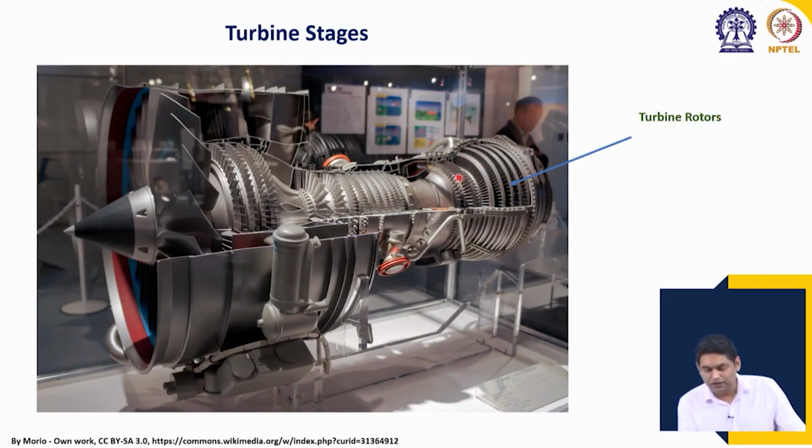Okay. And they also have similar blades, but the blades are more curved for turbine stages, and each turbine stage can undergo more pressure ratio, it generates more work as compared to the work input to a single compressor stage. So, fewer turbine stages are required even for industrial gas turbines, and for jet engines even fewer turbine stages are required. Okay.